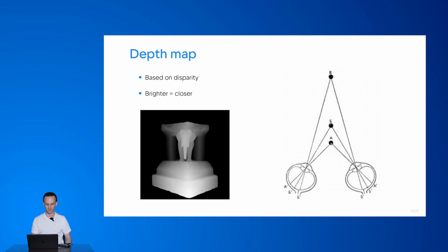An example of a depth map is given in the slide on the left. The main idea behind the depth map is that the closer the object, the brighter the color, and it's a metrical, or more adequate, representation of the distance. We can ask for a specific area in the depth map, so we can look for a certain pixel in it, and we will be able to find the distance in real meters, in contrast to the disparity map.